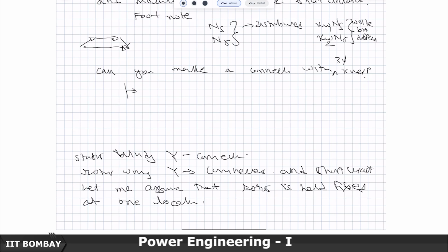But here the 3-phase windings are distributed in space around a circular region, and they carry 3-phase voltages or currents. So, it causes a rotating MMF wave, and if there is a rotor sitting here, let us say a piece of iron like that, it will try to align itself with that rotating MMF wave and just rotate. There is not even any winding, just a piece of salient construction of iron, and you can see that it will tend to rotate.